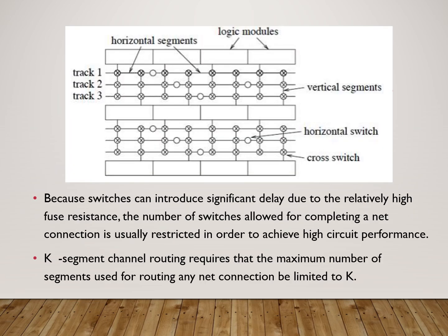See, this row-based architecture clearly shows that this full region is called the logic module, because this kind of row-based architecture is used in Actel, right? Only in Actel do we use this kind of architecture. In Actel, the basic programmable cell is called the logic module. So this is logic module 1, 2, 3, 4, right? We have 4 logic modules. And here also we have 5, 6, 7, 8, 9, 10, 11, 12. These are the logic modules.